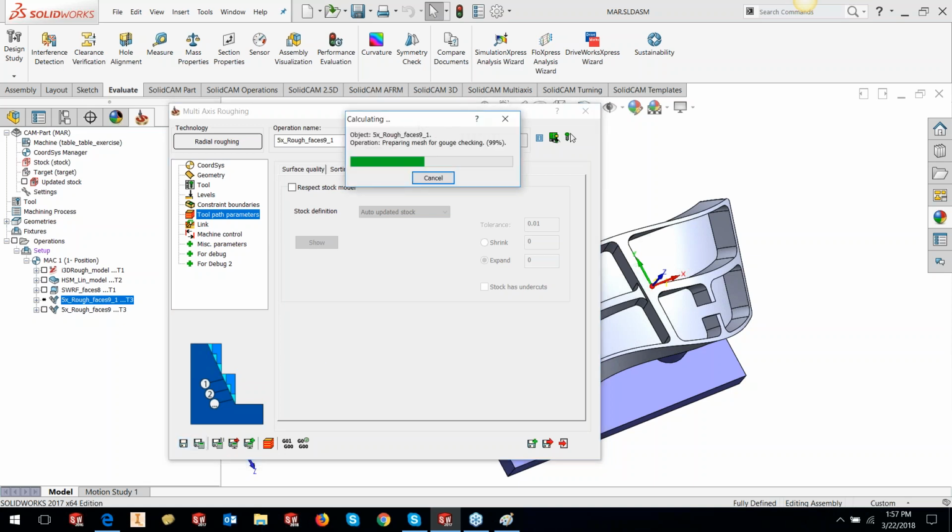Let's save and run the calculation. By the way, multi-axis roughing is also a great tool for finishing floors of several 5-axis components. You would like to finish a floor of a certain component and you see that you're not getting a right strategy, you can actually depend on multi-axis roughing to do the floor finishing. Because you can use either the adaptive strategy or the contour strategy, and you can get a very nice floor machined with multi-axis roughing.